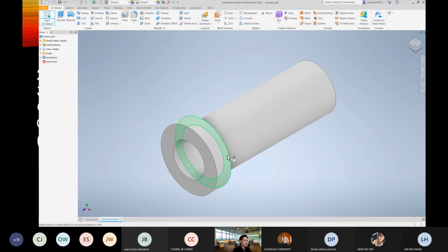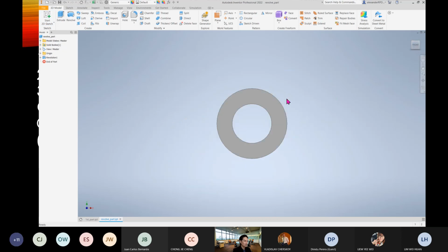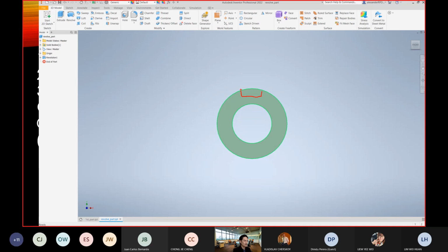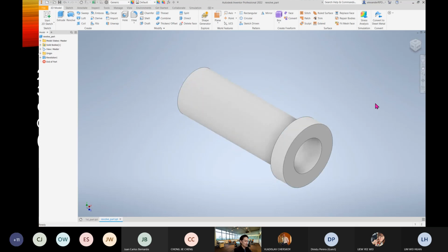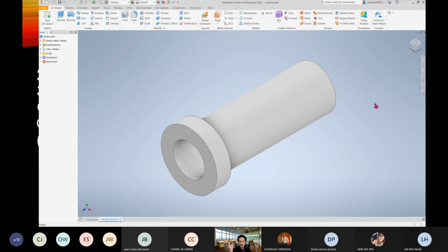Okay. So if I want to do a keyway like I just mentioned, I need to draw basically on top of here. And after that, I do an extrude cut over there. So, which means we need to create a plane. Okay, we need to create a plane for it. In other CAD software, creating a plane is definitely not something strange. But the way they create a plane, every software has a different approach. So I just want to show how we can do that in Inventor.